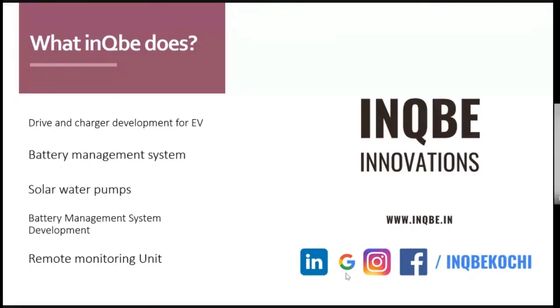That means even if it is a floating point algorithm, we can go for a non-floating point processor, because it will compute in between that time. For an MPPT-only application, we don't have to go for a higher capacity floating point processor. You can use non-floating point controllers, like the TI 28027. Even Arduino is able to do MPPT applications. But if you need higher computation accuracy and higher speed in MPPT itself, you can use STM or TI, so for higher computation speed we can use higher processors.